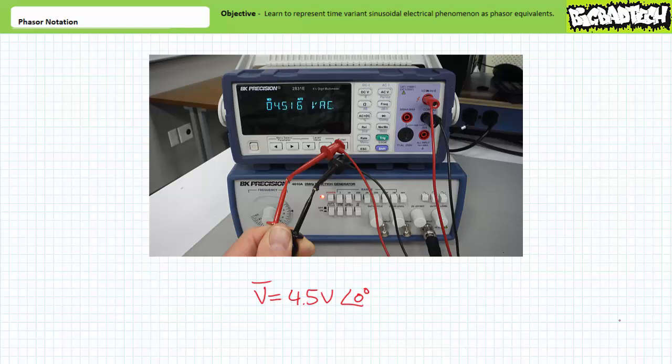Do we care about frequency? No, we don't. We're in the phasor domain, and we can just assume that everything has the same frequency, whatever it might be. The same thing can be said about ammeters. All AC ammeters, all the time, always display effective or RMS current unless explicitly stated otherwise.